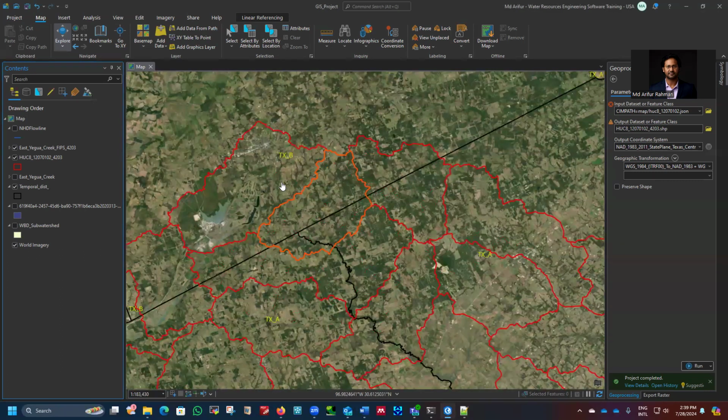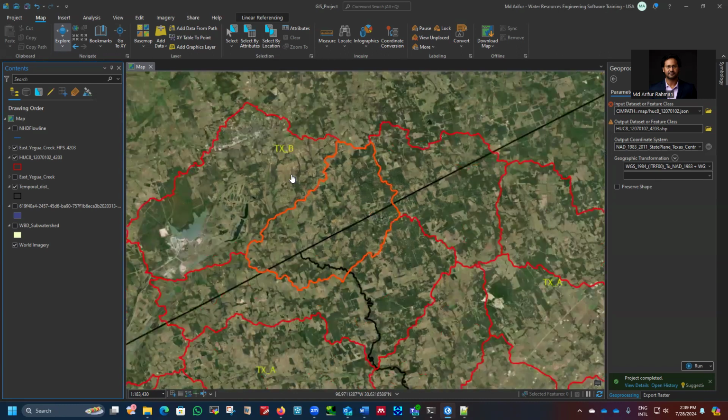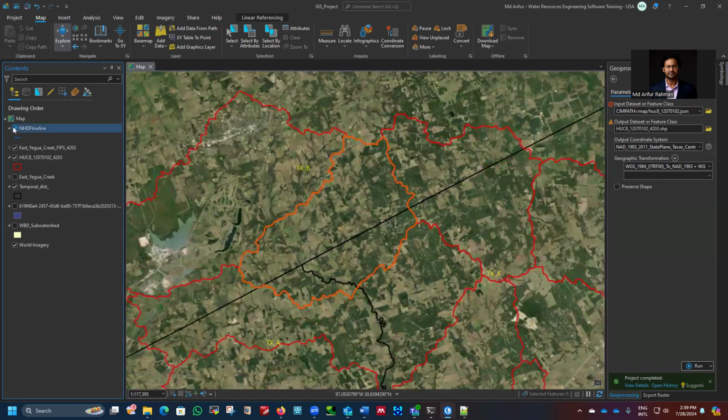And later on, we'll download the soil data from the SSURGO website, and I'll also download the land use and land cover data to create the infiltration layer to create the gridded curve number, because that's the method we're going to use here. And then we'll download the road shapefile. We'll download the stream shapefile, because we already have the streams. And then we need to generate our nominal mesh, and then we'll refine the mesh following the stream shapefile and also the roadway shapefile.